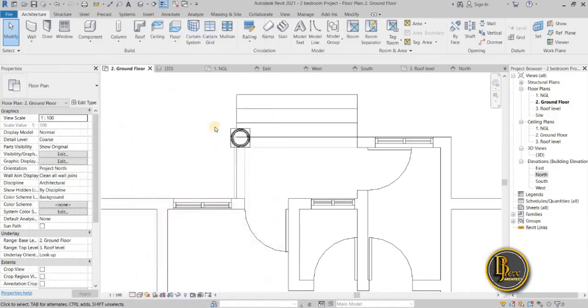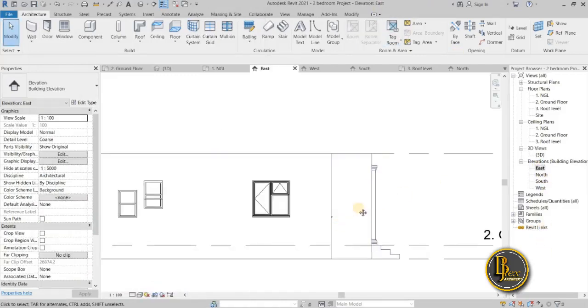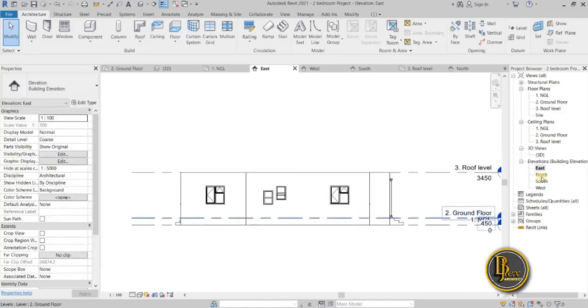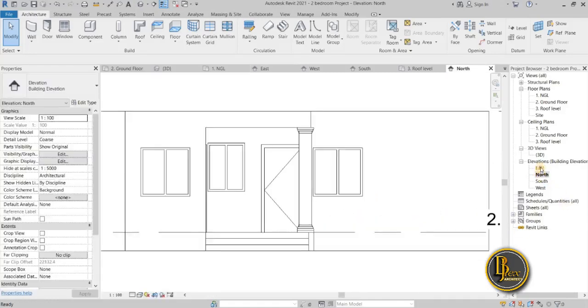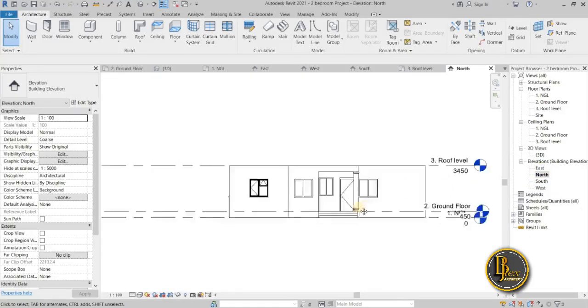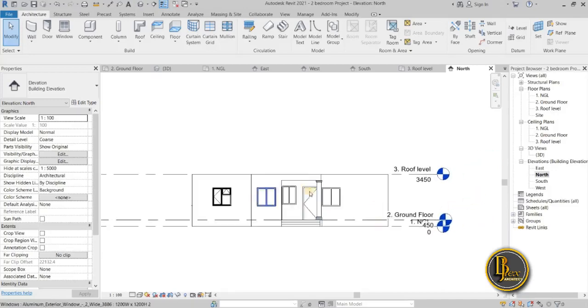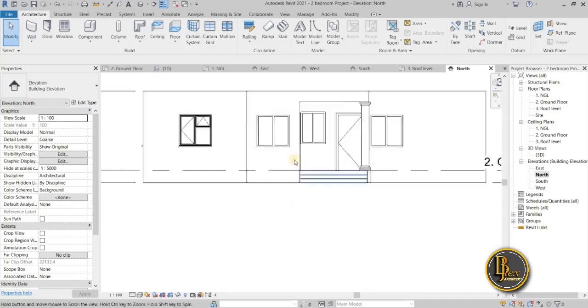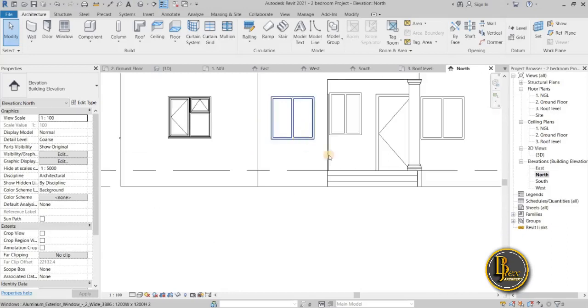Sorry it took this long to create all this, but you need to understand this concept of this particular way of creating columns and beams, because in Revit you'll be making use of sweep a lot. Especially if you are modeling your design from scratch up, you'll be using sweep a lot. So that's just it. Let's move this.